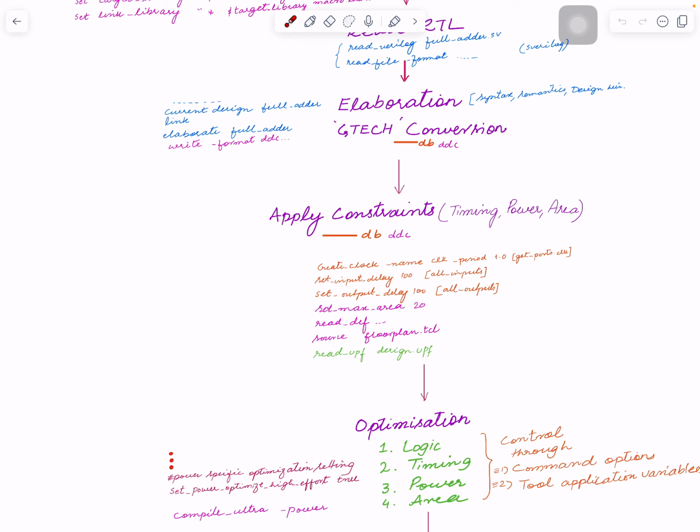And that is super good. At such an early stage as synthesis, tool can do optimization with close to final type of floor plan. Because of floor plan, it has to play this. These two ports are pretty far apart, so then it can optimize them better. So it kind of reduces the burden for the later stages coming in.